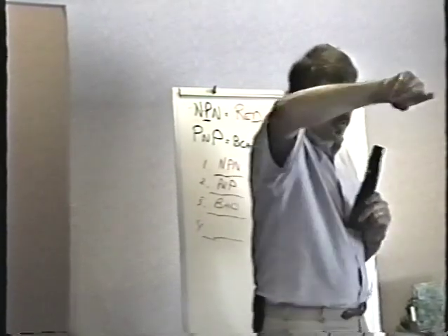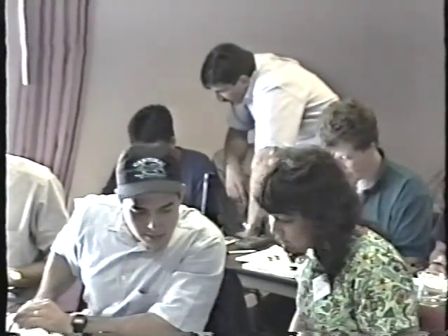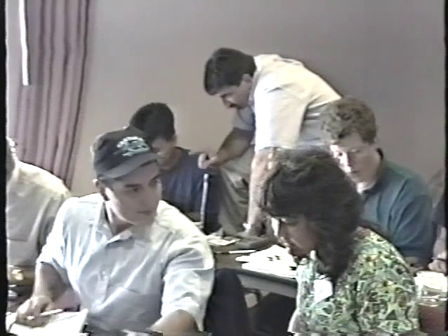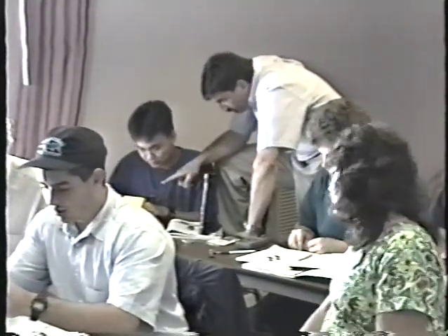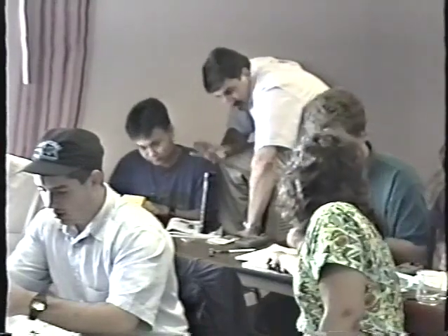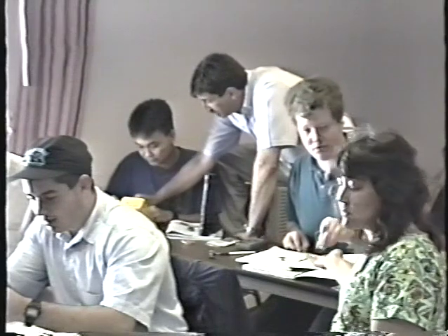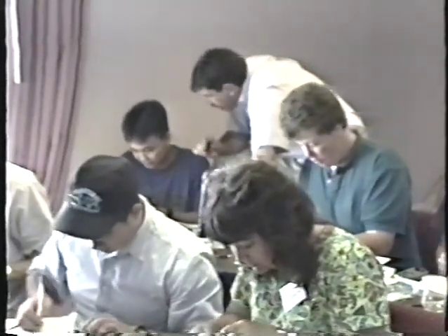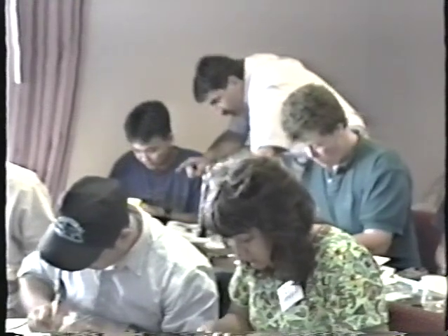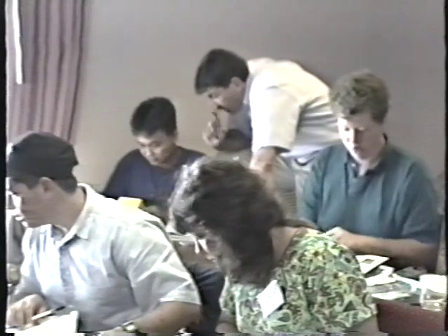Now I'm going to circulate around you, amongst you. Okay, start with the red on the base and the black on the emitter. You're getting a junction drop, 0.5. Leave the red exactly where it is. Don't move it. Move the black to the collector. 0.5. Same thing. So far, so good. Now leave this the way it is. Reverse the leads in your hands. Do the same thing you just did. This time we should get an open reading. Yes. Open. Open. Good.